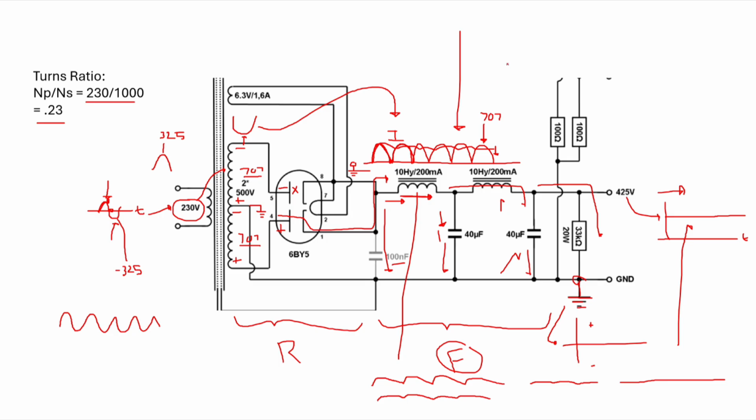So what you're going to affect, let me just kind of draw this for you, and I'm just thinking out loud here. So here's our rectified voltage. When you start filtering like this, you're never going to achieve the peak voltage. You're going to achieve something a little lower. So by the time you're done filtering and smoothing things out, the straight flat line DC you're going to get is going to be somewhere lower than the peak.